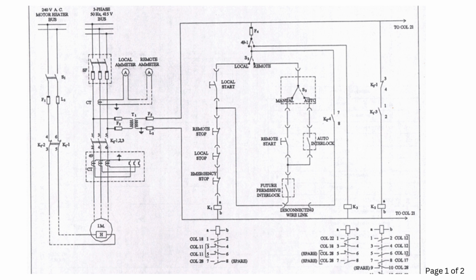When we talk about induction motors, the protection scheme depends on the motor rating and the application. Typically, large motors are protected by comprehensive induction motor protection relays. However, small motors up to 100 kilowatts are protected only by a thermal overload relay or HRC, I mean high rupture capacity fuses, against short circuit or overloading. In this diagram, the motor is connected to a 415 volt 3-phase switchgear, and it is expected to operate in